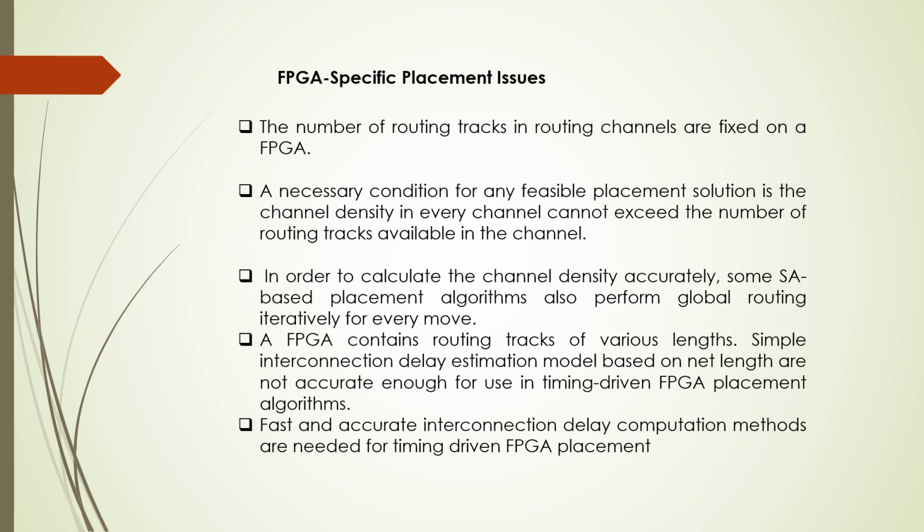Coming to the FPGA specific placement issues, the main placement issues include the number of routing tracks in routing channels, which is normally fixed on an FPGA. The second issue is the condition for any feasible placement, that is the channel density. The channel density in every channel cannot exceed the number of routing tracks available. So the first thing is routing channels and channel density.